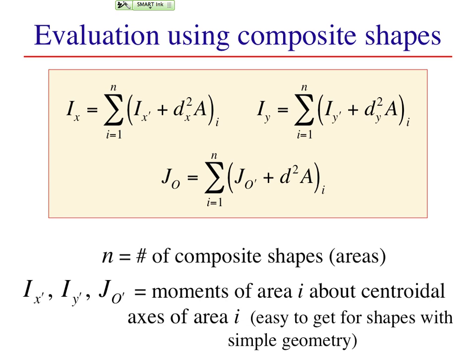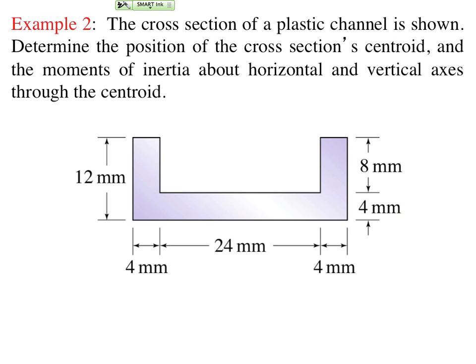Although it's useful to have it for an alternative integration procedure, the parallel axis theorem is more useful in evaluating area moments for cross-sections that can be represented as a superposition of simple shapes. We previously used it to generate expressions for Ix and Iy of an I-beam. It isn't always the case, however, that we can see by inspection the location of a shape's centroid.